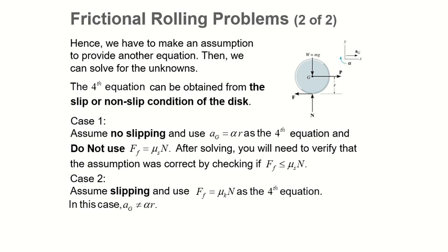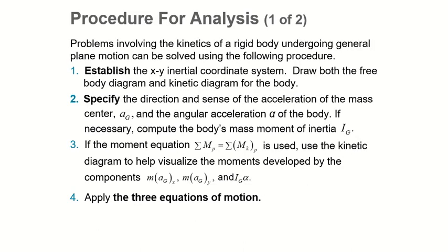There's something else that is contributing that force to slip. Okay, the procedure analysis, not necessary, just listen. We usually break it down into an XY inertial coordinate system, and then we draw a free body diagram and a kinetic diagram for motion, about to move or start moving. This is the balance, the free body diagram. And then we throw in what we know and find what we don't know.